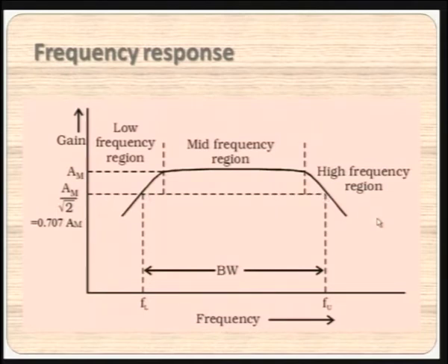At low frequencies, the gain slowly starts increasing when the frequency increases, and the case is just the opposite in the higher frequency range, and in the mid frequency it is maintained more or less constant. So, the effects are like in the lower range there is one reason, and for the higher frequency region the reverse is the reason, and in the mid frequency region one effect is cancelling the other effect. This is what we could understand at a basic level.